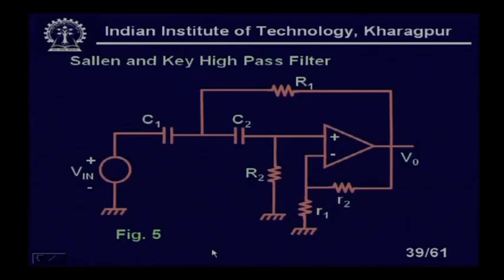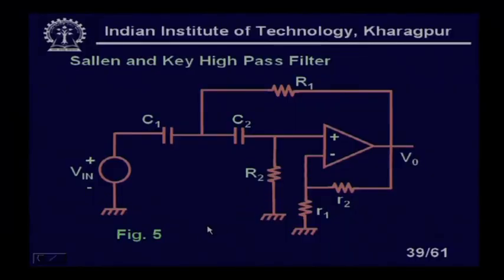So, it is fixed. Now, these are high pass filters; you can see we have interchanged resistances and capacitances, right. So, if you interchange the resistance and capacitance, I will get a high pass filter. You see, these are very handy circuits. If I have a high pass filter and I know the design equations, I can make my own filter. It does not cost much, not more than 5-6 rupees. Only the op amp is costly, the resistance and capacitance can be ordinary, right. But we need a certain amount of tuning. You will find that whatever prescribed center frequency, pole frequency we have asked for, we may not achieve that particular frequency. We need a little tuning, because the sensitivity of this type of structure is quite high.